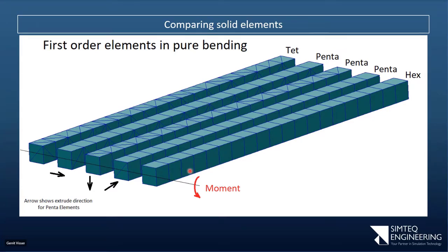And what I've done was, I'll show it in a table a little bit later, I've normalized the displacements all relative to the X mesh, so you can compare what the deformation was. The stresses, I've done a hand calculation and I've normalized relative to that. But for the shear calculation, for the deformation, it's actually slightly more complex. There are some things you have to take into consideration. What I don't show here is I've just, for a reference, added a single beam and applied exactly the same load, so you can see what the effect of this would be.